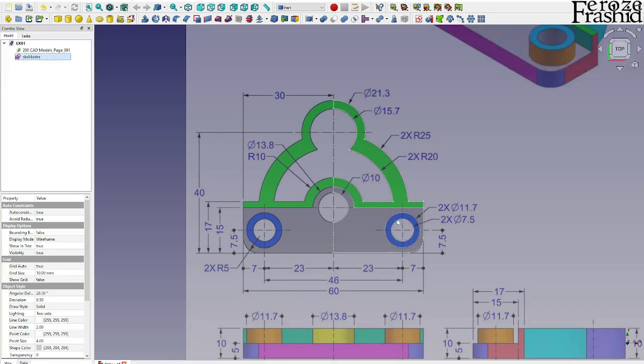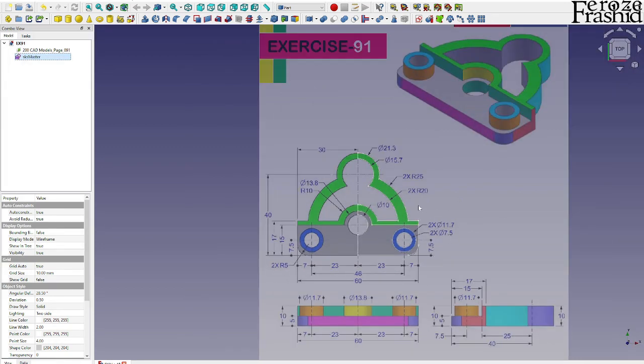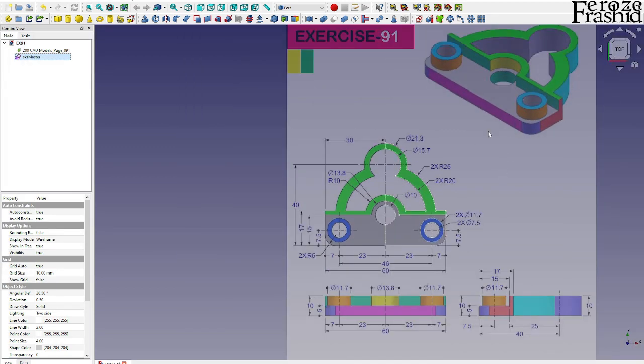On this one I want to do both things on the same plane. So I'm going to copy that and paste it 2 times and hide this one. This one I'm going to name sketch upper part, and the second one sketch lower part.